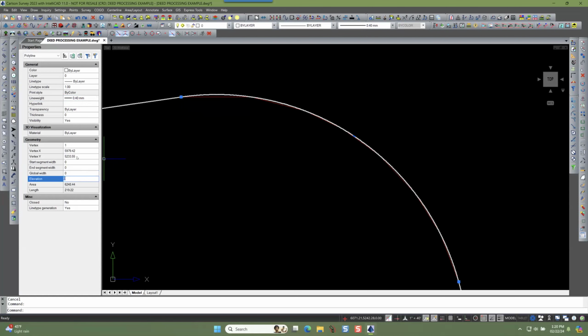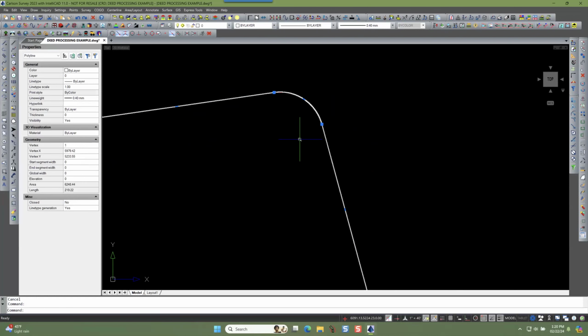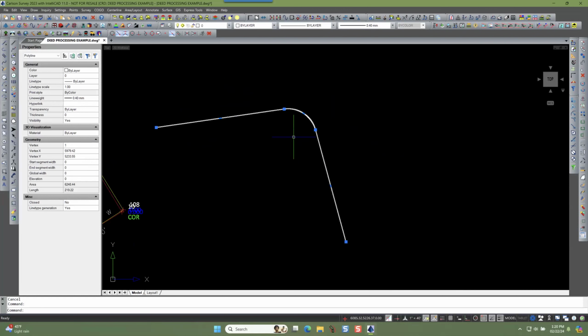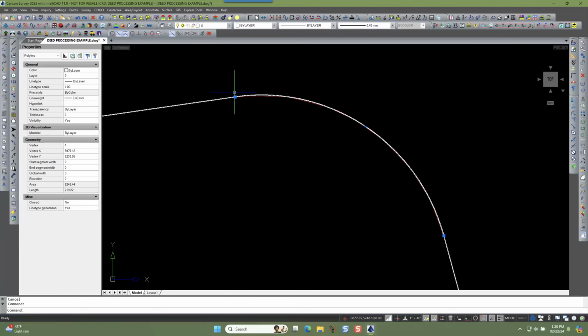You can see down here my properties to the left. But if it were a 3D polyline, it needs to replace this circular arc section, which you can see if I select that original, it has the PC and the PT, and it shows you where the midpoint is, but it's only defined by the start and end point and the radius distance.